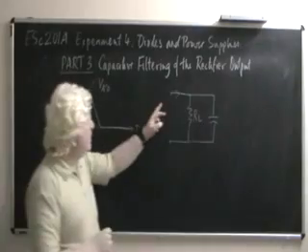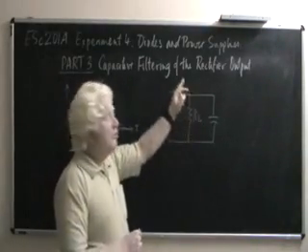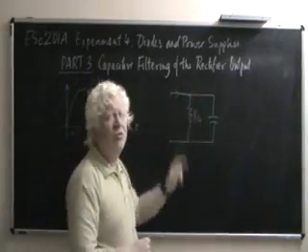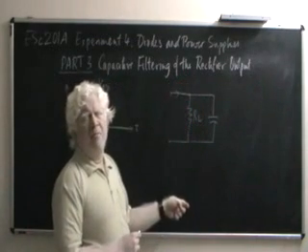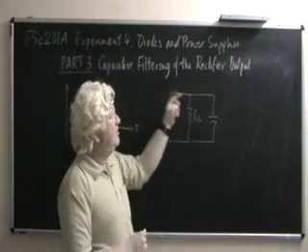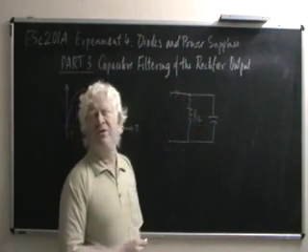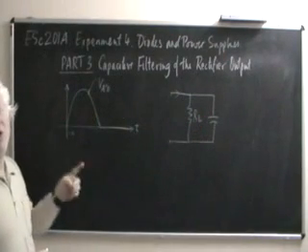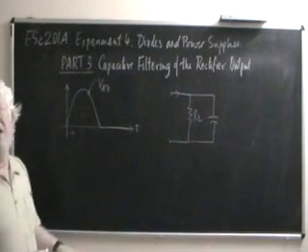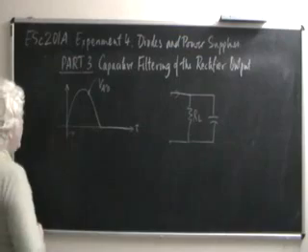Simultaneously, the rectifier output is also forcing a current into the resistor. But while passing current through the resistor, the same voltage also charges the capacitor, almost instantaneously. So let's now plot the capacitor's voltage as a function of time.